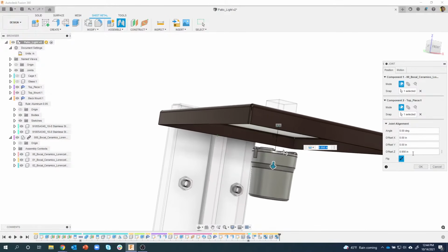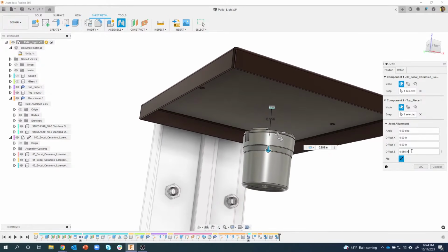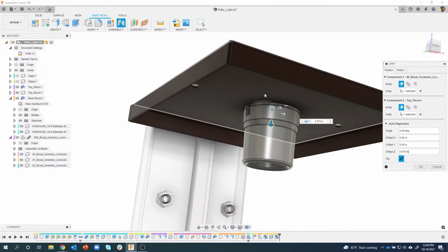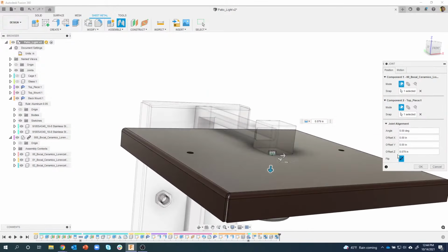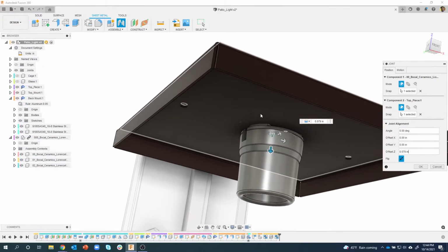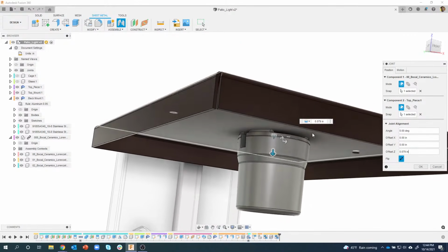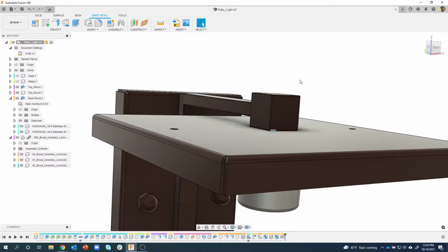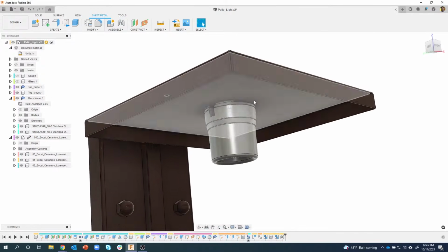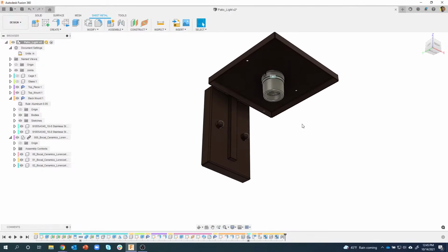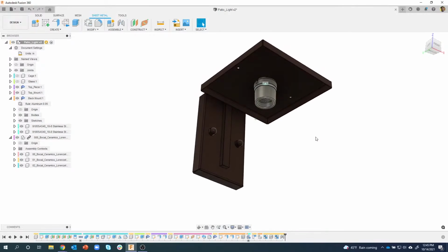Okay, and right now it's almost an inch, basically. Well, all I have to do is paste, so Control V, and it pasted that measurement in there, and it moved it down 0.079. So those standoffs are exactly flush with that face. I'll say OK, and we've now created a rigid joint of the socket to the top there.